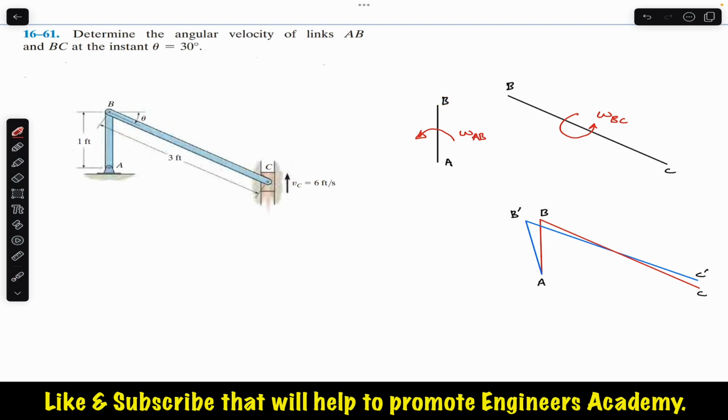We can show that the velocity of point B will be in the horizontal direction, making 90 degrees with link AB. And the magnitude of this velocity will be equal to the radius times the omega of link AB, since this VB velocity is only due to the angular velocity of link AB.